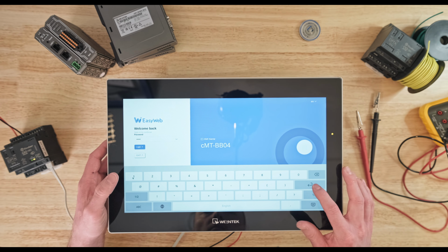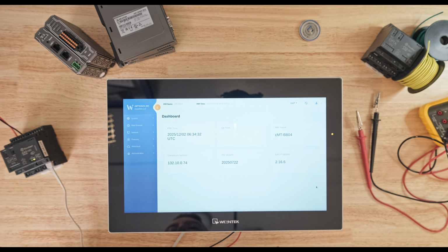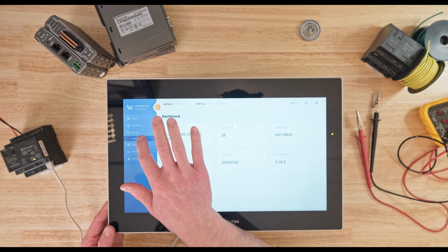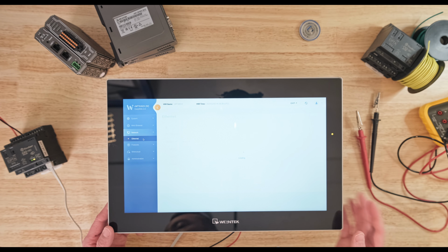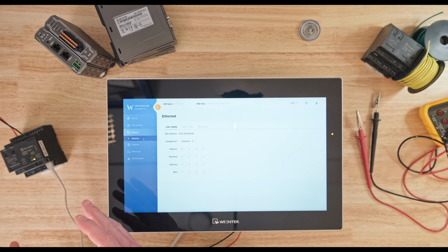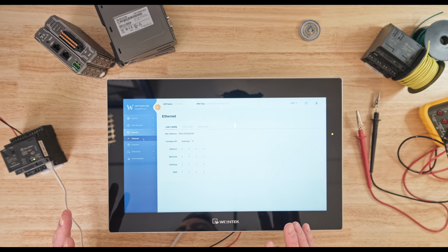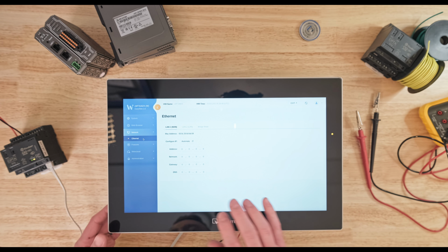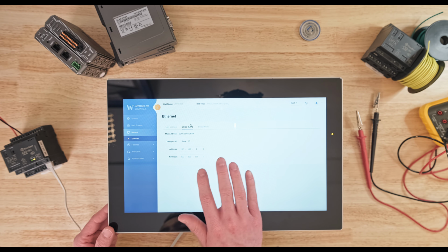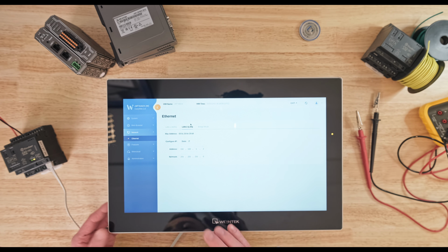And really the last feature that you need to know about in order to set up your web panel is the network tab here. Just as we want to connect the web panel to our web-based HMI, we want to make sure that the web-based HMI has a known IP or known URL, and that our web panel has a network configuration that will allow you to reach that URL or that website.